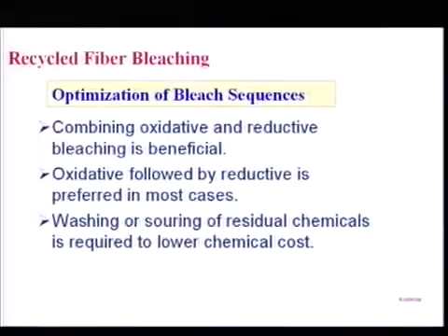Washing or neutralization step is very important. You need to quench that residual peroxide. You do not want oxidative chemical to go and eat your reductive chemical. So, you need SO2 water for a neutralization step or a washing step to take away the residual peroxide in the system.